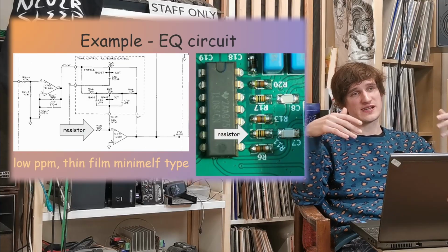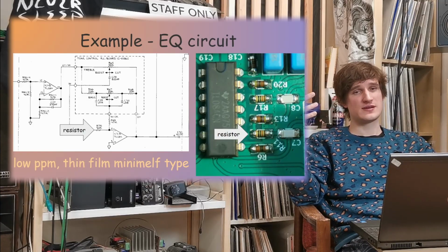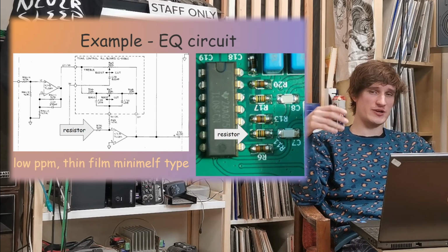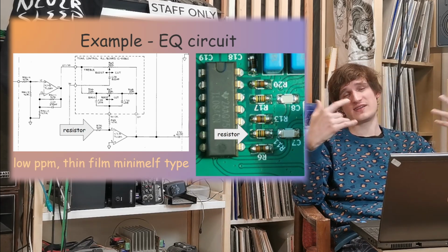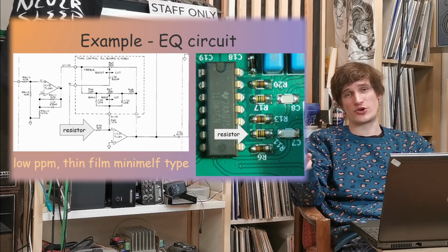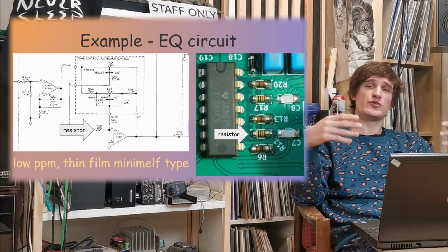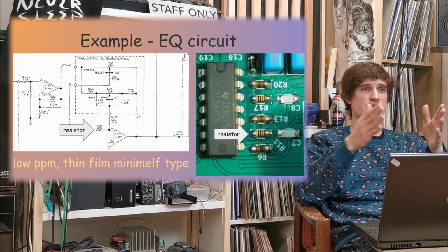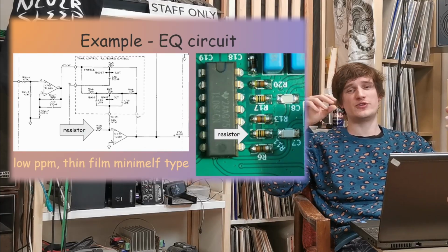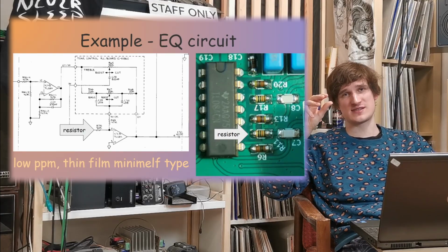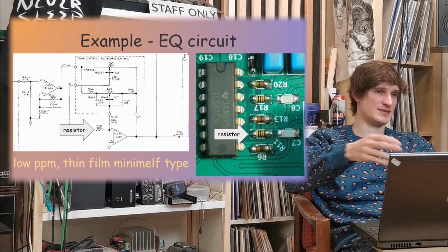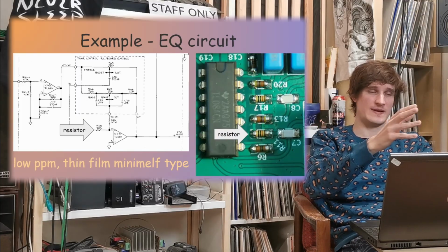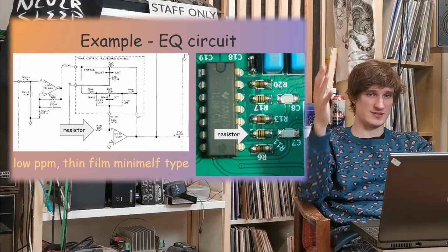When you deal with circuits like minus 60 dB of THD, circuits that have a significant amount of distortion or noise, you don't really have to take much care about resistor quality, because the effect of the resistor will just flatten those distortions and noise generated by active components and circuitry.